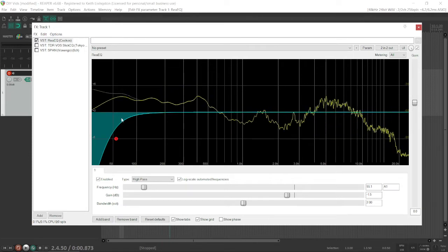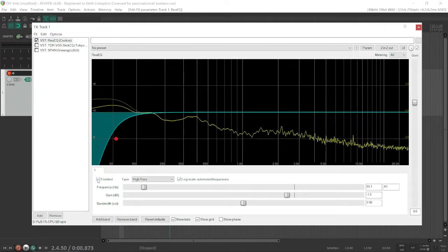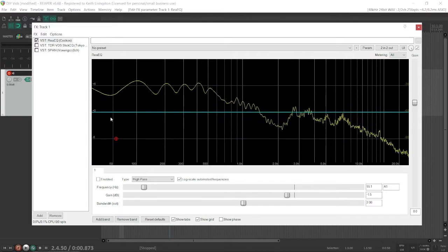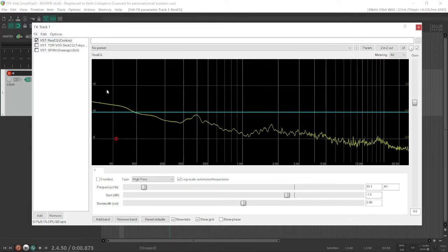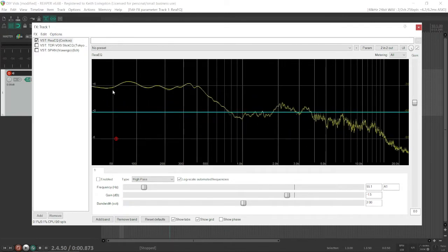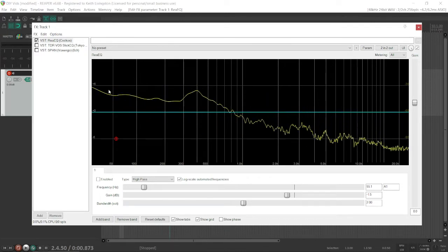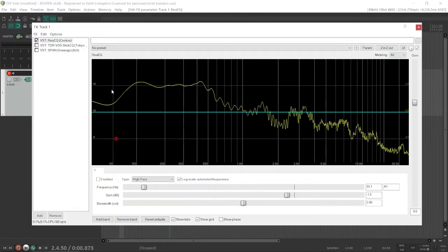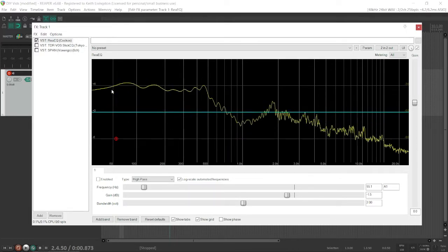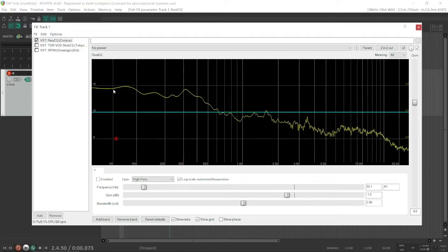If you notice this, so if I turn this off again, you notice all this low end information. It's between 100 and 20 hertz down here. Now, where is the bass guitar? The low note on a standard tuned bass guitar is 41 or 42 hertz.